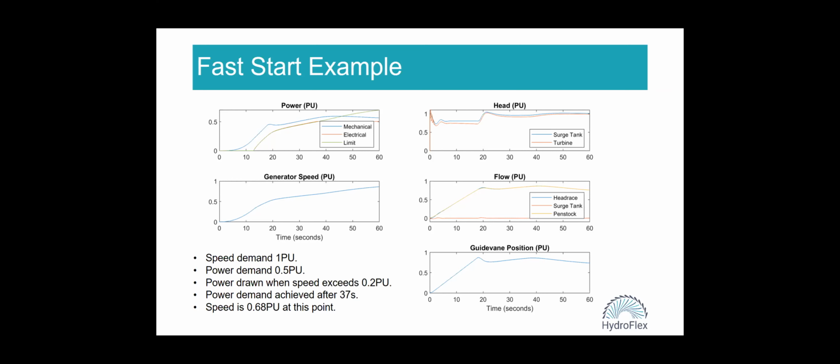Of course, the more stretching we have in the hill chart, the higher efficiency and less pressure pulsations the turbine will have when operated at off-design operating conditions. So it is highly case dependent. We cannot draw a general conclusion here. It doesn't work that easily for all sorts of Francis turbines.